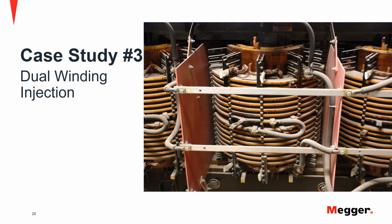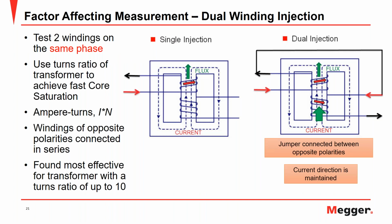Now, let's move on to case study number 3. This case deals with dual winding injection. Let's try and understand the concept of dual winding injection. In this method, we test two windings on the same phase. So let's say you're testing the B phase. You will be testing the high voltage and the low voltage winding of the transformer.